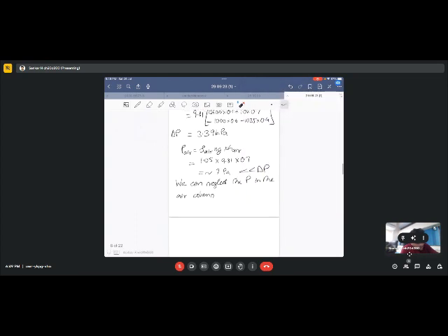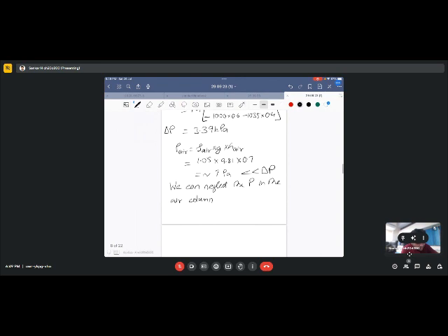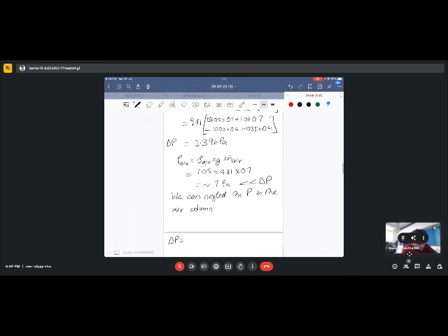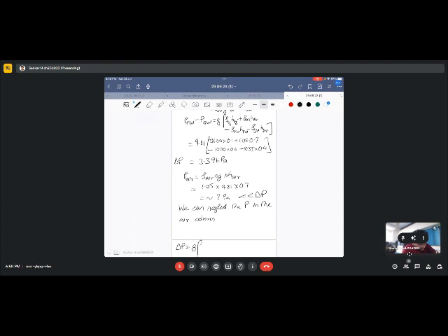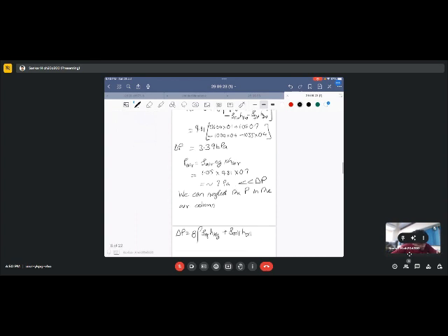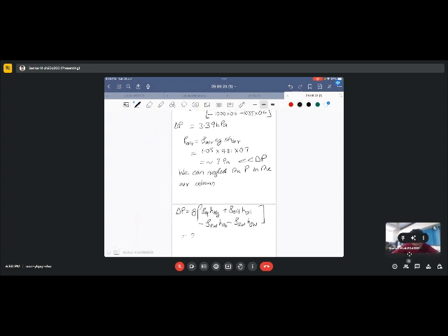So the solution effectively remains the same, saying that delta P is equal to g times ρ_Hg h_Hg plus ρ_oil h_oil minus ρ_freshwater h_freshwater minus ρ_seawater h_seawater. Again, if you try to solve this equation, you will get a very simple answer.